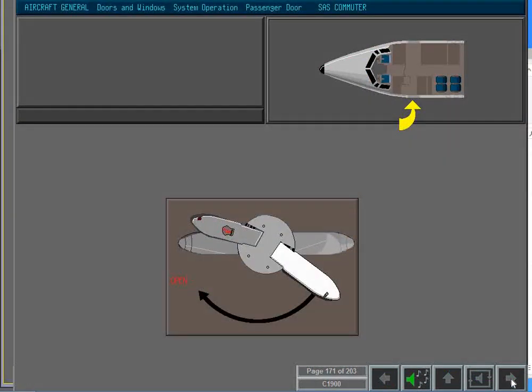The passenger door handle contains an integrated push button for lifting the hinged door handles. Now locate the integrated push button. To open the door, the handles are pulled and turned 150 degrees clockwise. Pulling the door enables it to open under its own weight. An electromagnetic brake limits the speed of the passenger door free fall.